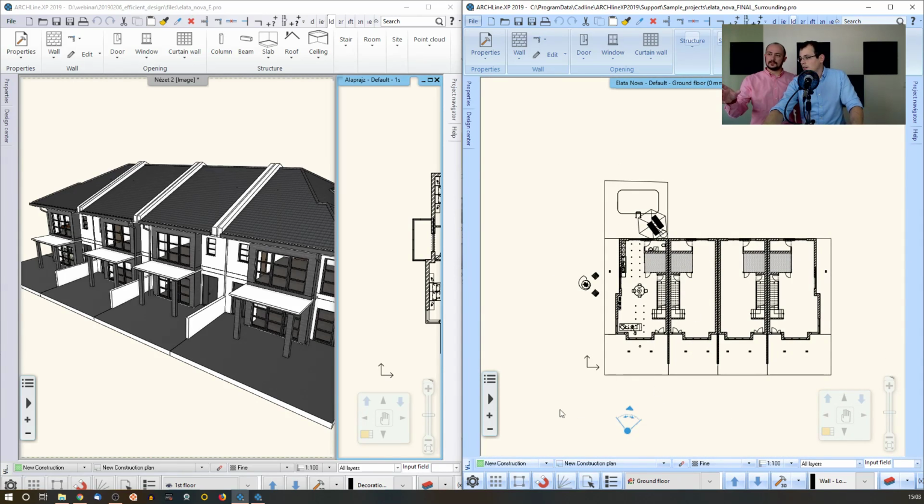How did you start the second copy? You just have to start ARCHLine again. There's no command to do that. No, you just double click on the application and you start it. You can start it as many times as you want, but you have to be cautious about this. This is a CAD software, so running it 2, 3, or 4 times might have a heavy toll on your CPU. That's not something that you have to do all the time, so that's not the tool for simultaneous planning. But this is a good way to get data from one stage to the other.